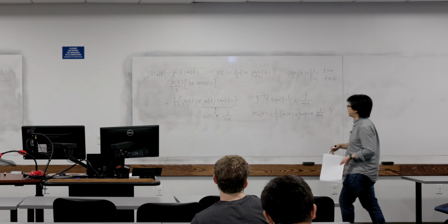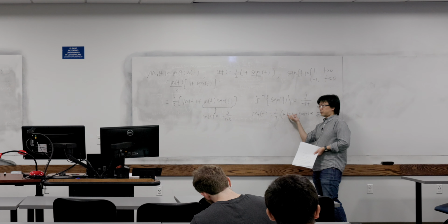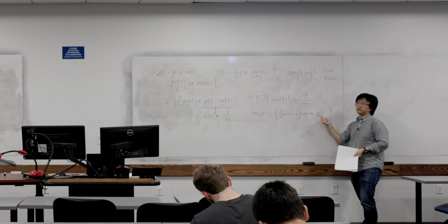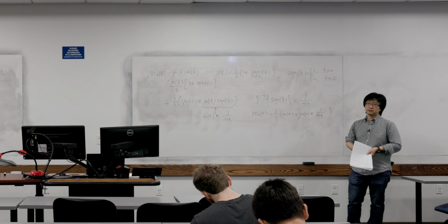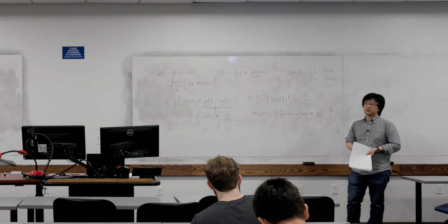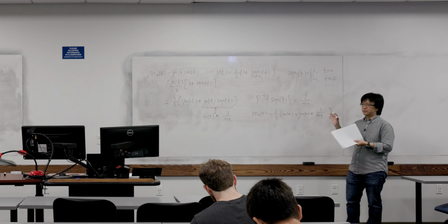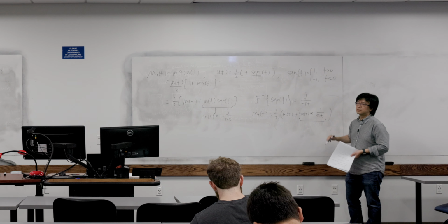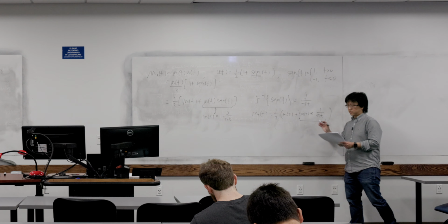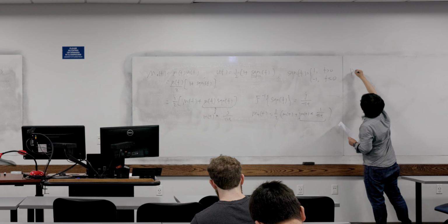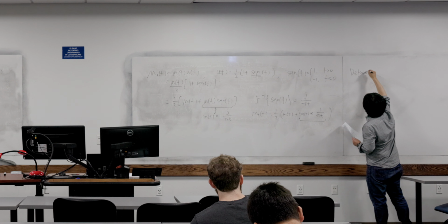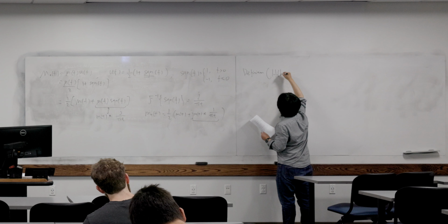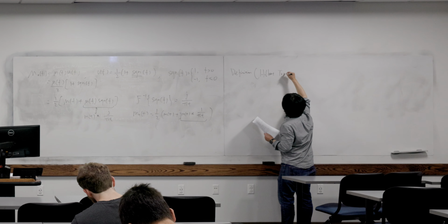So basically in the time domain, we use our original signal, multiply by j, m of t convolved with this signal, and then we can get half of the signal. Okay? And why I want to write it in this way is because this is a very famous convolution, so it has a special name. It's called the Hilbert transform.